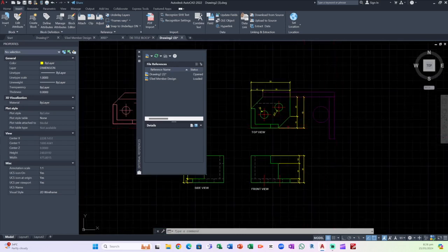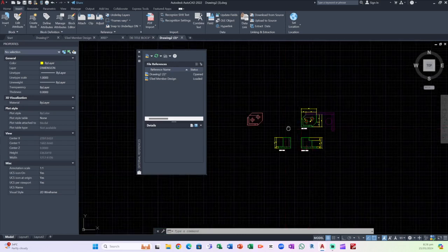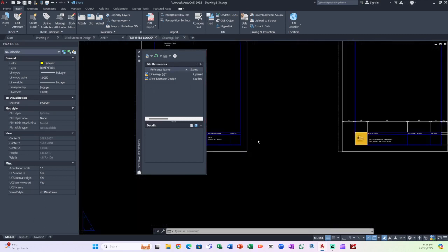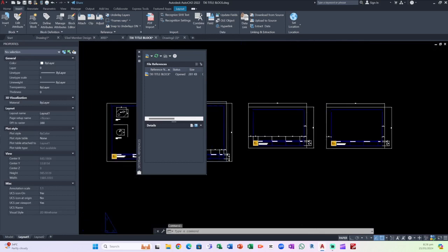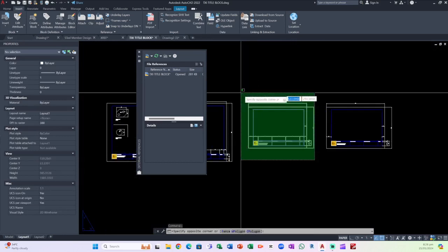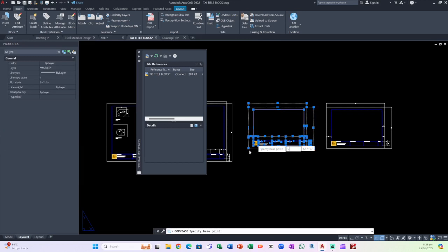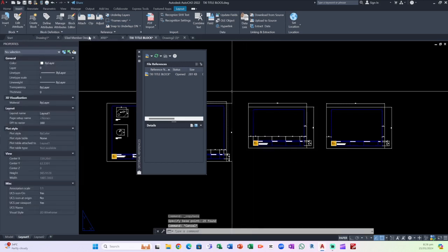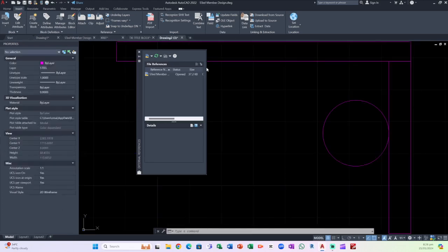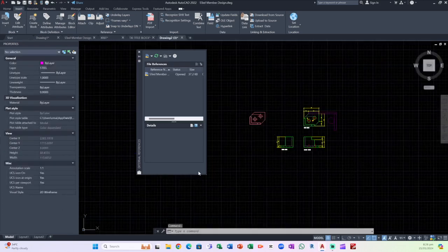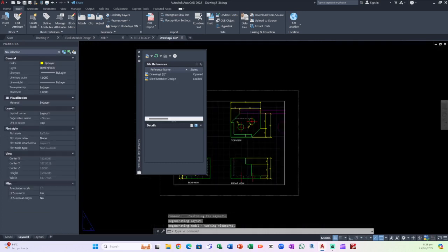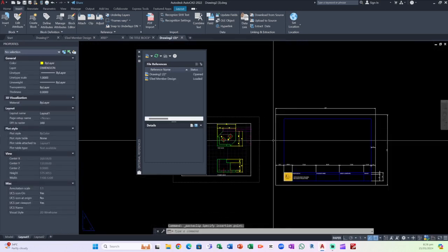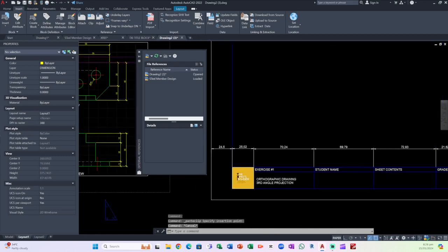Another thing, okay, so we have to put that in the title block. So we already have the title block, which is already here. Okay, so just copy this title block, and then Control C. Okay, and then going back to the drawing that we are working on, this drawing tool. Okay, going to the layout, click the layout, and then paste. Okay, now you have this title block.